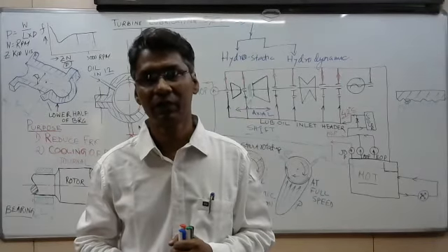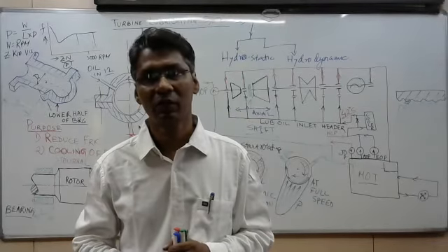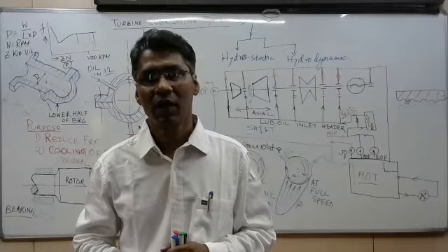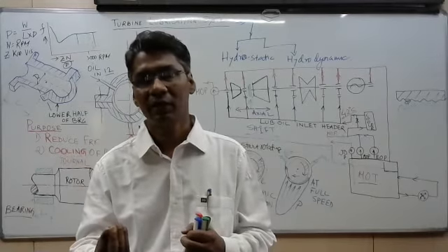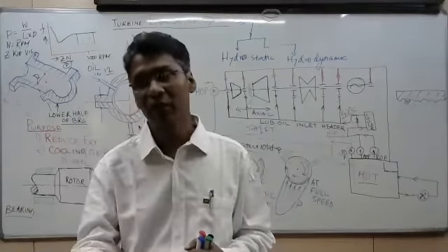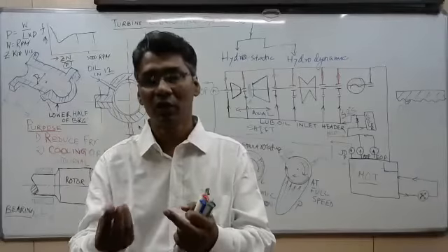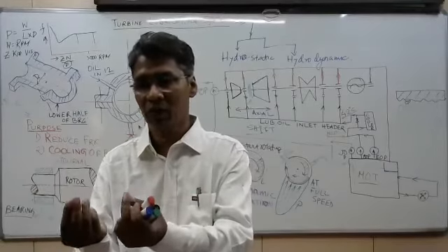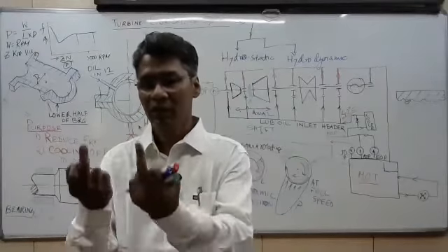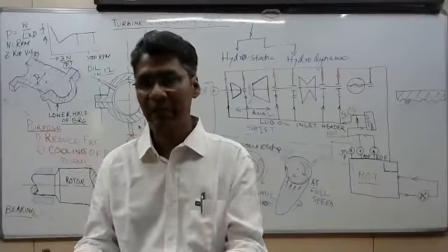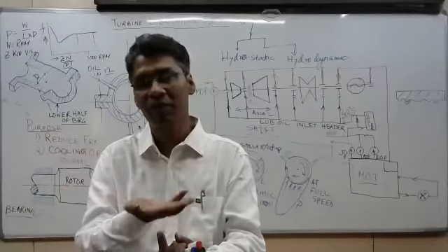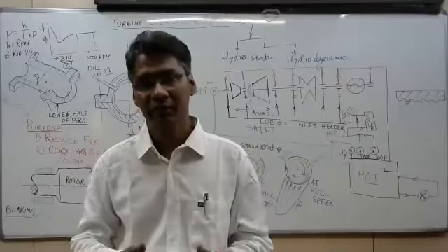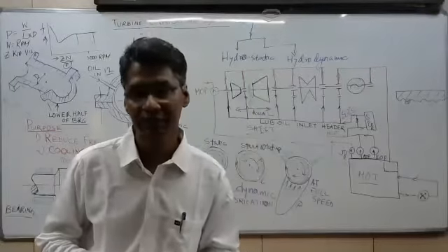Please explain hydrostatic action once more. Hydrostatics is very simple. You are providing, suppose, hydraulic pressure to lift the oil. We are giving several oil holes below the bearing and providing high pressure oil to maintain an artificial high pressure oil film to start rolling. So that is hydrostatic lubrication.